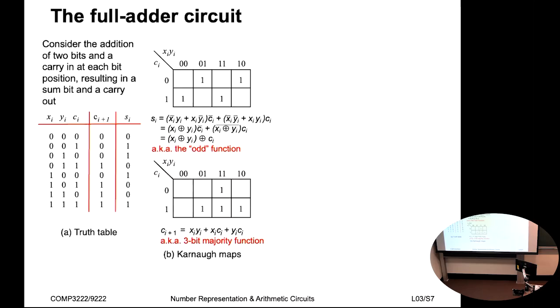And if we've got a checkerboard pattern in a Karnaugh map, there's nothing we can do. We can't simplify. We can't combine. There's no neighboring ones, either horizontally or vertically adjacent, that we can combine and then use the uniting theorem on to simplify. And so all we can do is list out all of those min terms that are covered.